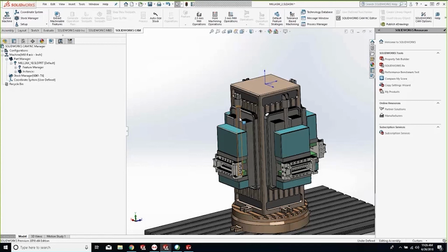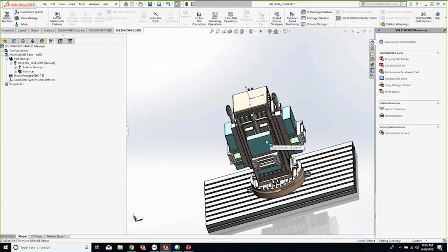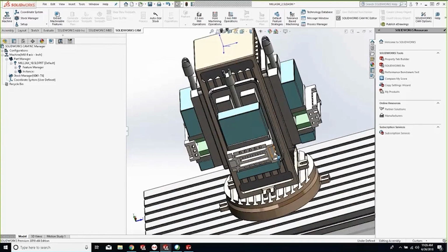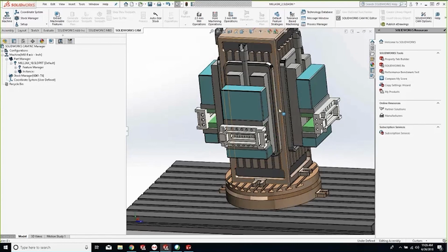And for me, being able to have an accurate setup or an accurate Toolpath simulation, we want to see all the stuff that we have sitting on the machine out on the shop floor. We want to see it within our CAM tool, and that gives us the ability to make sure that we're getting accurate Toolpath simulation. We want to make sure that our holders are not running into the vise, not hitting the corners when we're rotating, not hitting the end of this piece when it kicks from this piece over to this piece to machine. Without working in an assembly and without being able to interpret those multiple bodies and what is a fixture versus what is a part, we don't get any of that feedback, and we need that information to make sure.